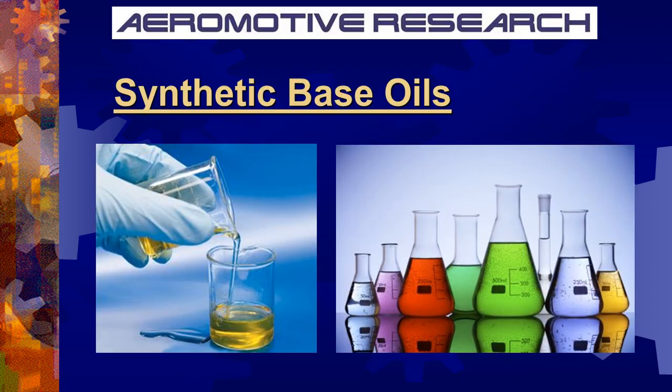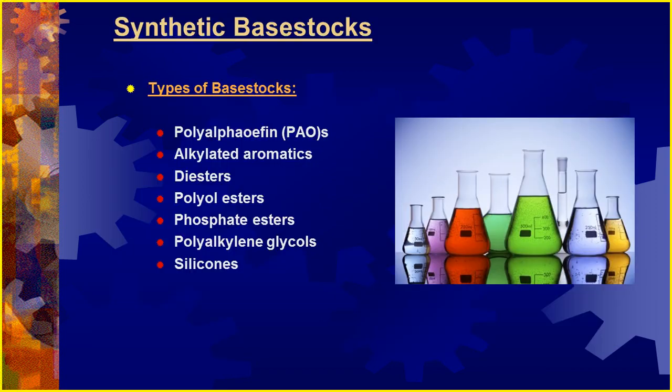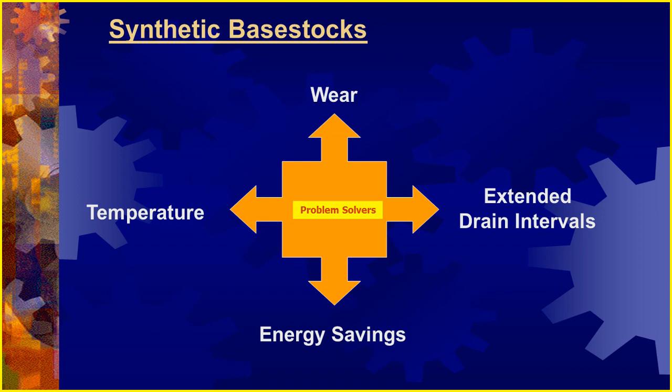So let's get into your synthetic base oils. Now, synthetic base oils or base stocks are going to be your PAOs along with your diesters, polyol esters, polyalkylene glycols, and silicones. It is a tremendous problem solver when it comes to temperature, energy savings, extended drain intervals, and wear.